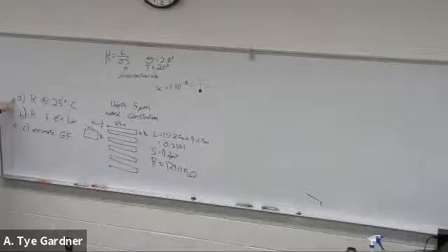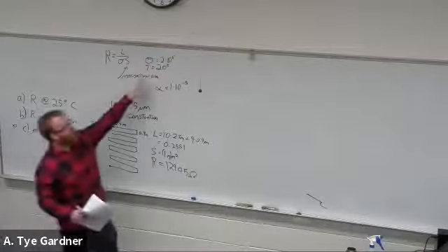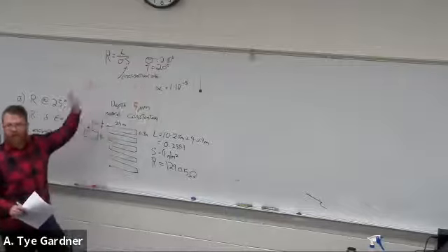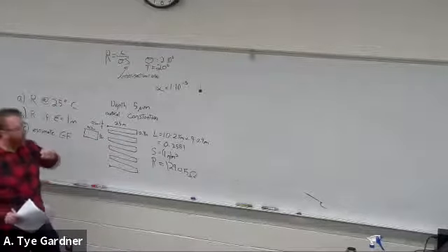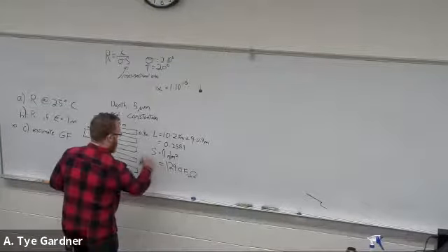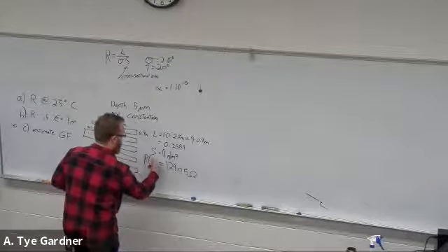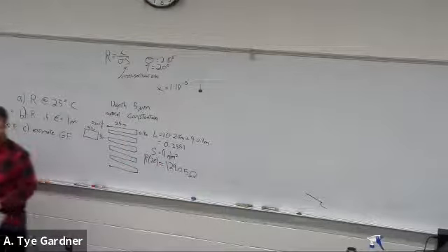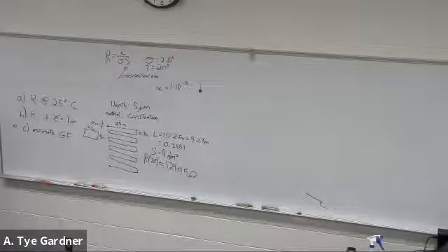Now, let's calculate R at 25 degrees C under no strain. You have everything you need. We just did that without compensation. So temperature, we're going to fix at 20 degrees C for all of the conductivity and everything else. That R that we have is at 20 degrees. So that's our T naught, yes, that's our R naught.